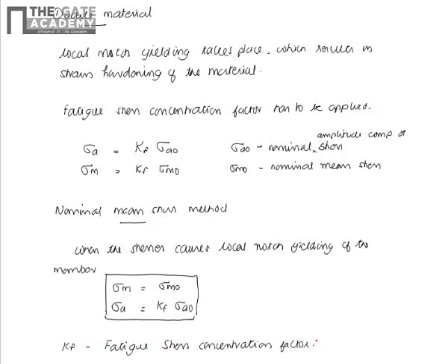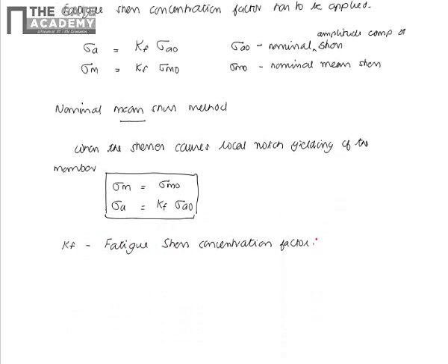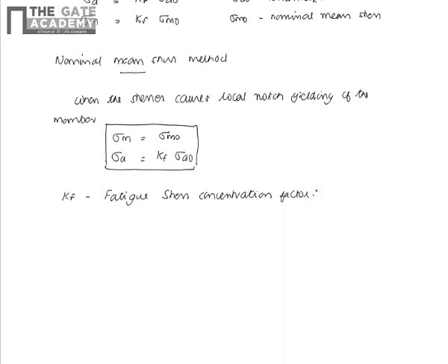In the previous module, we have seen what a fatigue stress concentration factor is and how much it differs from the theoretical stress concentration factor. We have seen that the fatigue stress concentration factor is related to the static or theoretical stress concentration factor by a parameter called the notch sensitivity of the material. So we can summarize as follows.